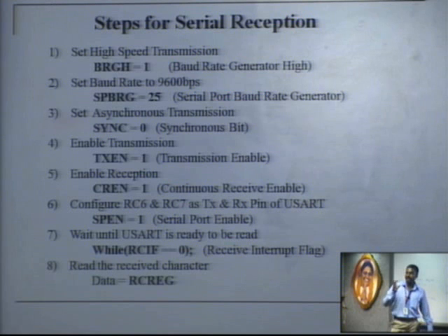When I am telling transmission or reception, I am telling with respect to PIC. When I am telling steps for transmission, it means PIC is transmitting to something. Similarly, reception means PIC is receiving. So reception means when it is receiving some data, that data should be present in some register, no? Then only I can read that register. That register is your RCREG.